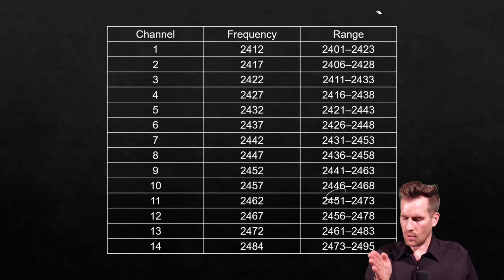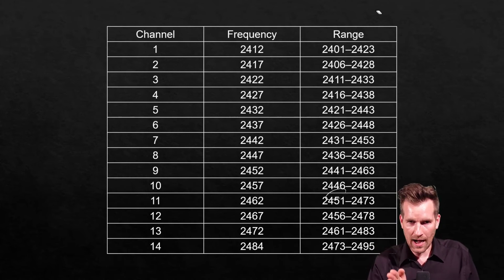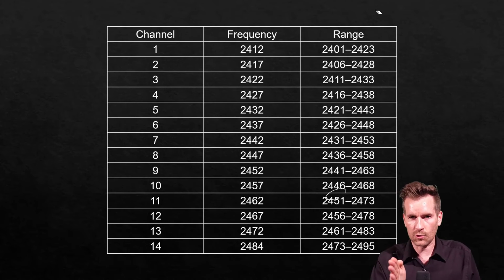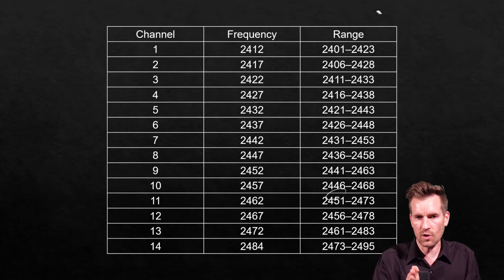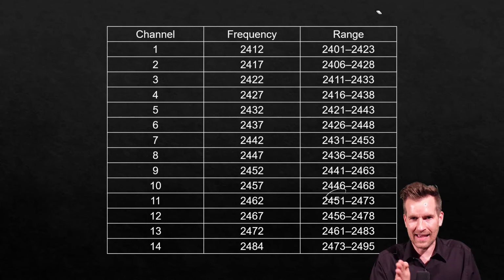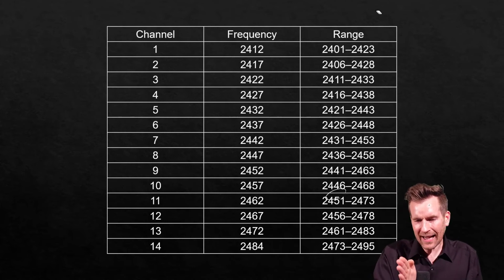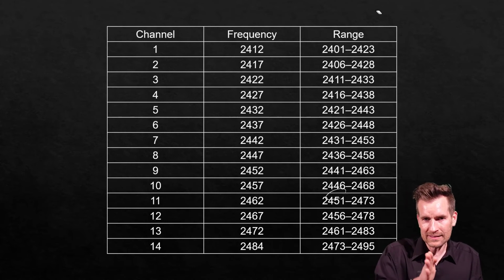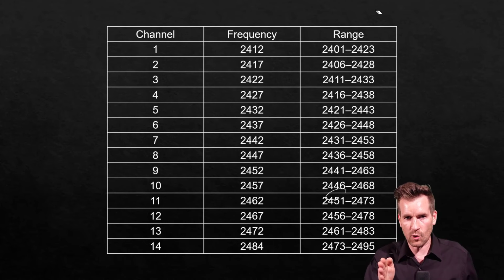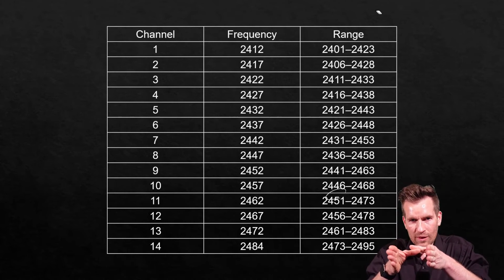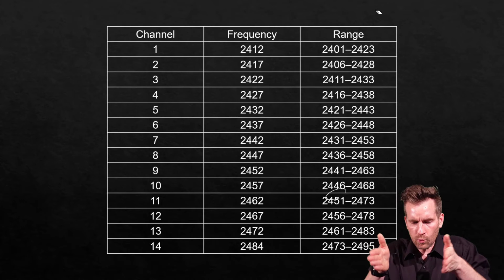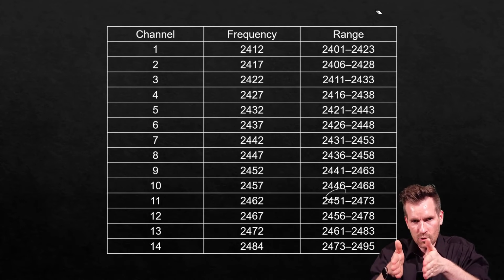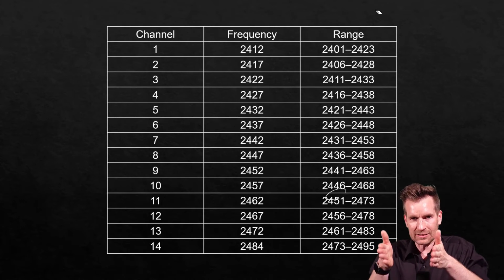So we've got that frequency that we're operating at. Then we adjust it one way or another to represent those 1s and 0s, to represent the data being sent across it. So we actually need some of the frequencies before it and some of the frequencies after it. We need a band. For this channel, we need a whole range, a spectrum of frequencies, to adjust to send this data across.